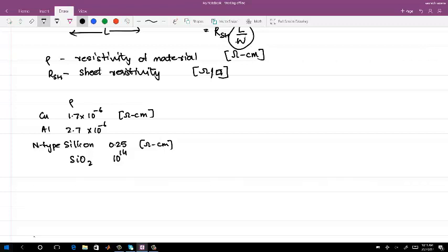Now when I say the resistance process variation is important, if I say it's an N-type silicon, it has a finite resistance. What do you think can change the resistance value? Doping concentration, the doping profile can change the resistance, right? So all these process variations can easily give you plus minus 20 to 30% of resistor variation.